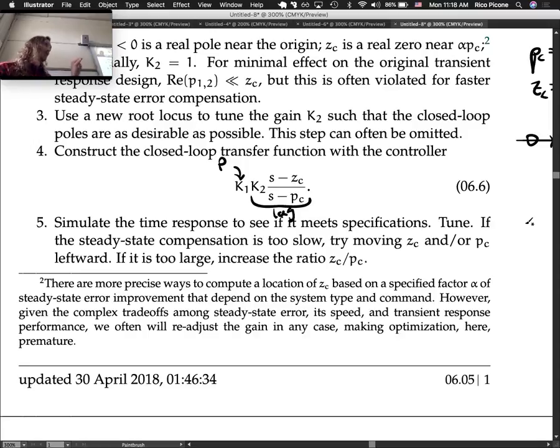So it'll give you resistors and capacitors and inductors, and you size them appropriately, and it will compute the error and then scale it by whatever your gains are for your controller, by the sizes of the capacitors and the resistors, and it'll put out a voltage that will probably need to be amplified to go into the motor. So that's the process in terms of an analog controller, but we don't typically do an analog controller anymore.